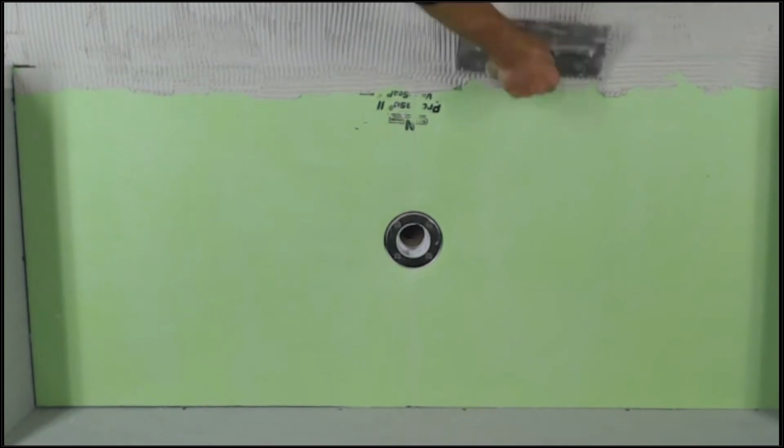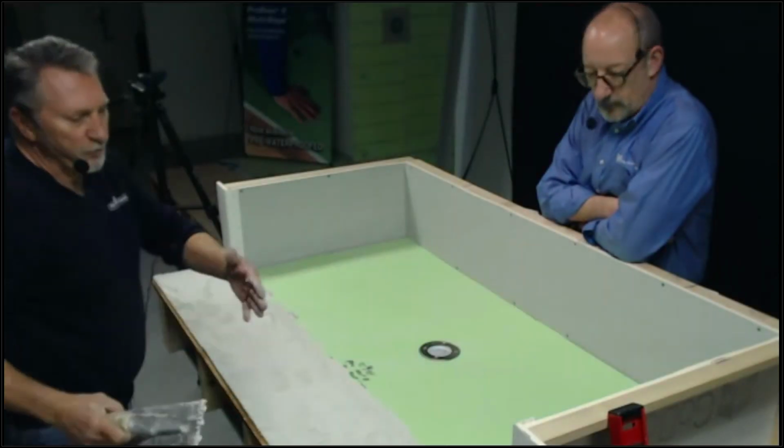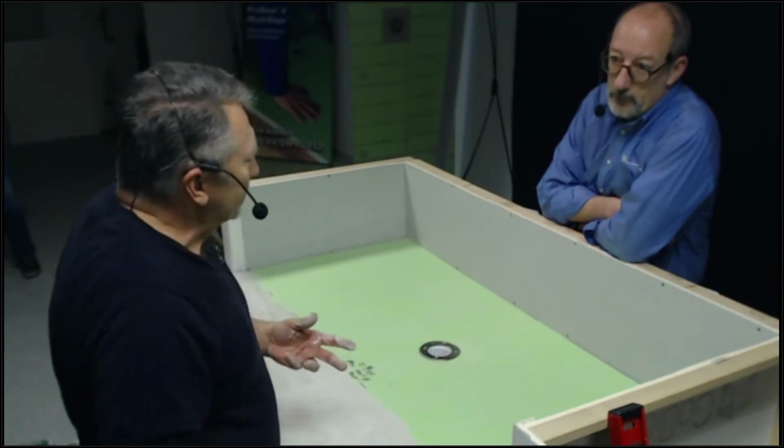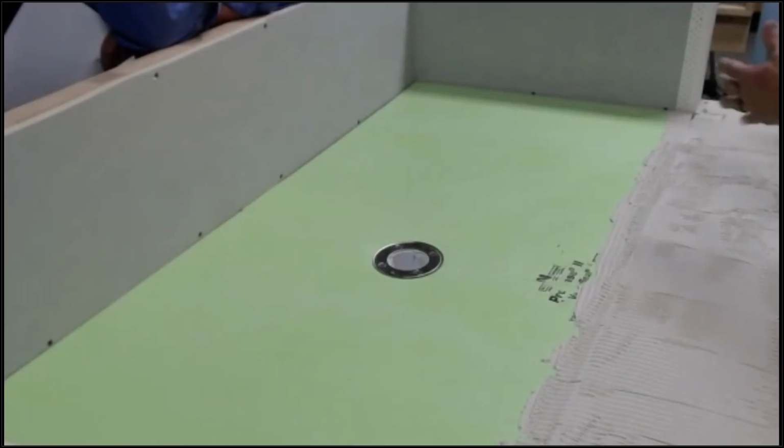Make sure it's rolled in nice and even. Okay. Now, you notice here with my knee walls or wing walls, if I'm going to have, say, a tile cove base, you'd like to waterproof that area because you know that area is always problematic, especially with water migration. That's drywall right there. So I'll put a little thin set right there.